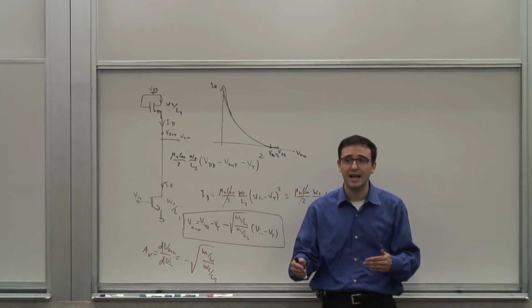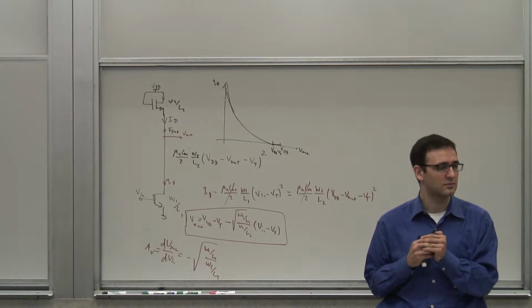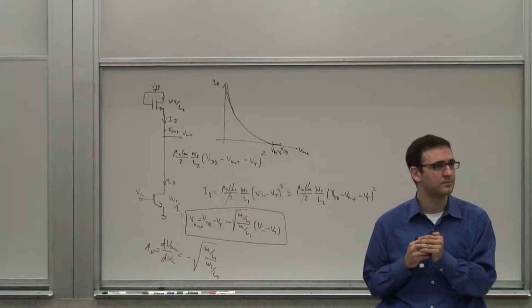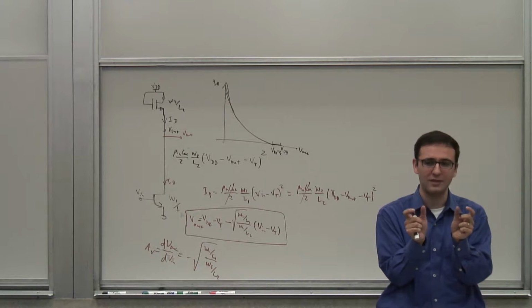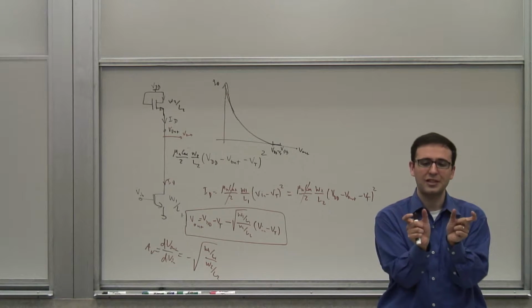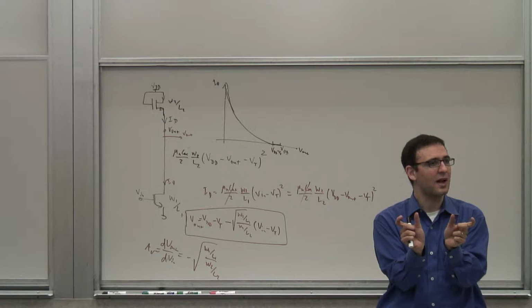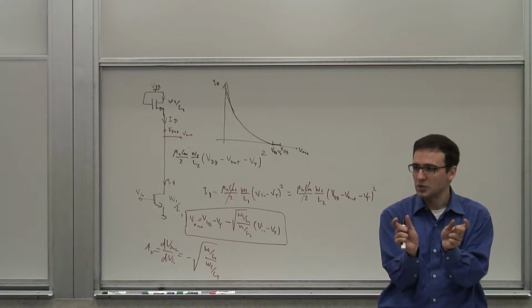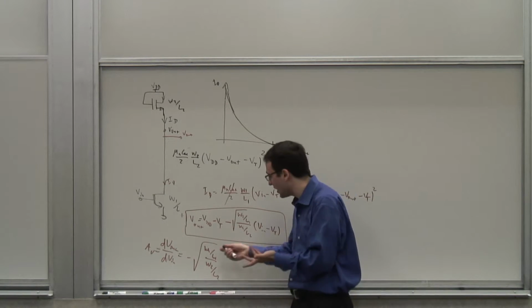And not only that, it's determined by the ratio of some physical dimensions. So if all of a sudden, for some reason, your lithography or your etching process runs a little longer or a little shorter, all of them scale up or scale down by a certain amount, and the error will be much smaller when you calculate the ratio. So in that sense, it's a good thing that it does not depend on other things.